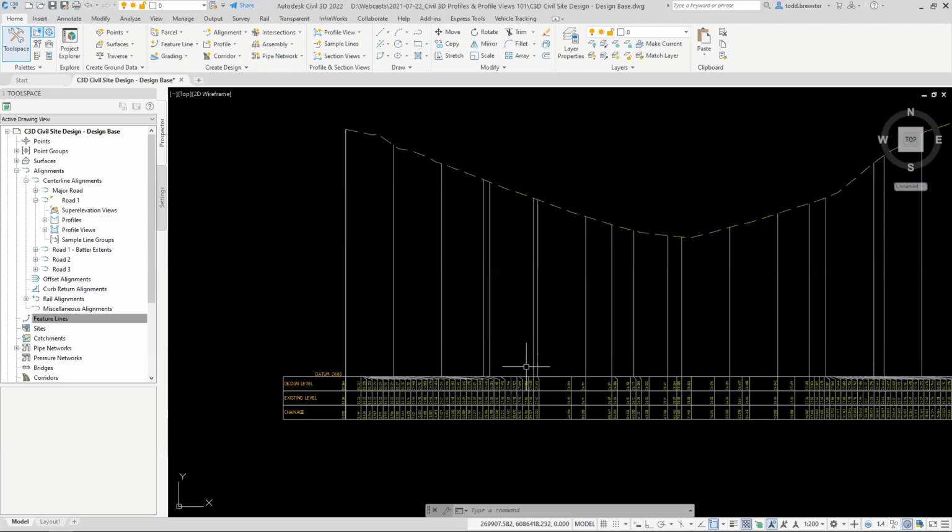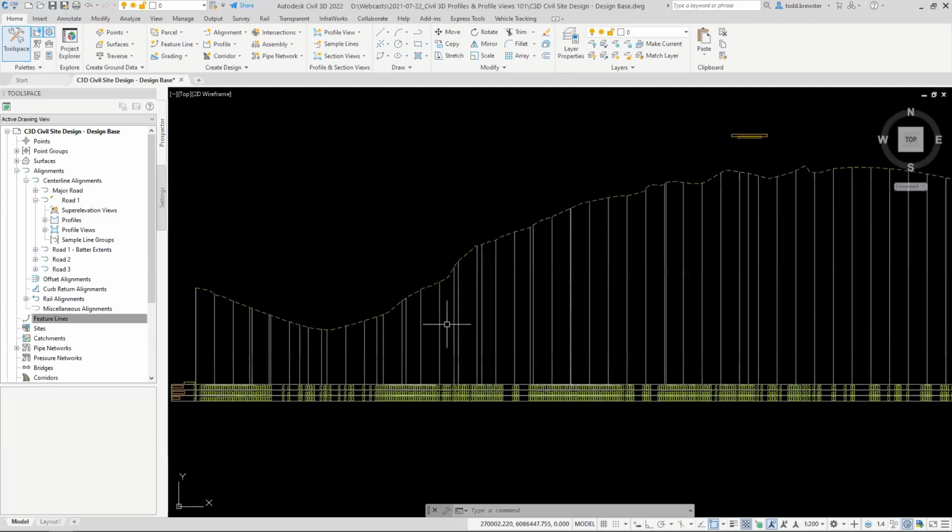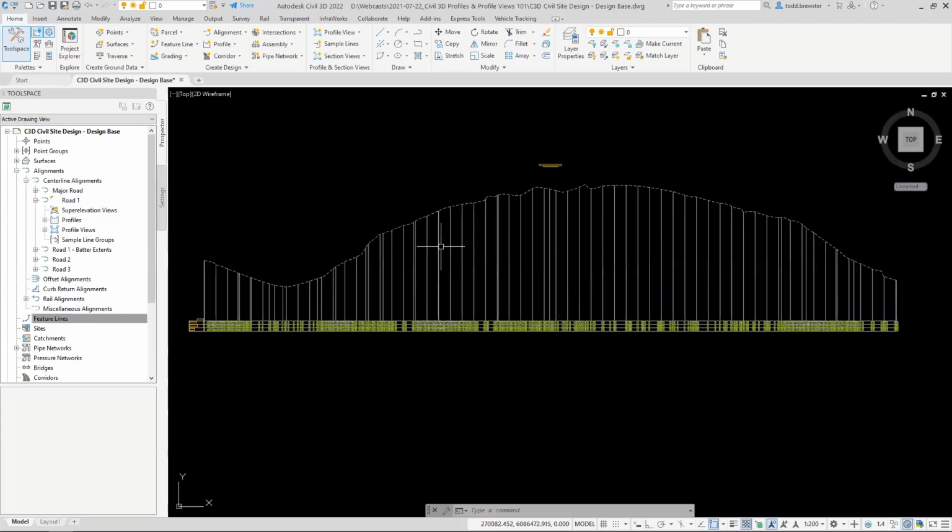All right. Design profiles. So a design profile is basically the vertical design that you would apply if you're building a corridor, or maybe even using the basic controls for a grading object if you're going that far. You could even use it to represent a simple pipe network rather than actually extracting pipe network objects. Whatever it is you're actually trying to model, the design profile is your chance of applying that information. So I'm going to do this based on the premise that this thing is actually a road.